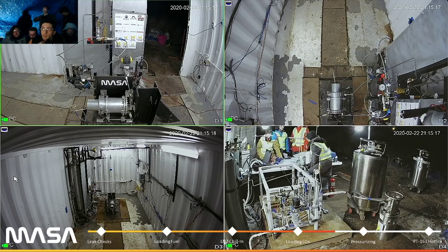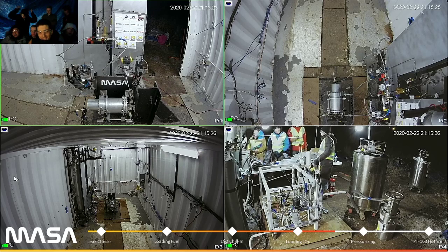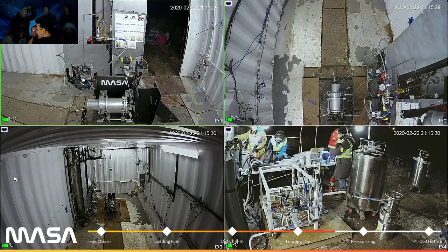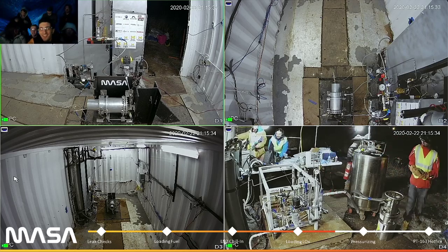The fuel valve in our setup right now that we've been using for all the hot fires is actually an in-house built valve, and that works very well. The liquid oxygen valve, on the other hand, is very difficult. We've gone through several prototypes. They've all somewhat worked, somewhat had a lot of issues, but the fuel valve works very nicely. However, we're currently working on a new fuel valve, and a new LOX valve.